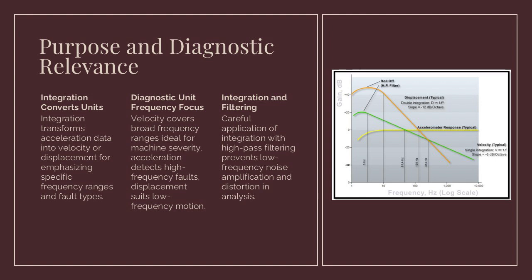Acceleration is ideal for detecting high-frequency faults such as early-stage bearing or gear defects, while displacement highlights low-frequency motion, making it suitable for slow-speed machines and journal bearings. By integrating data, analysts can tailor their analysis to the specific fault conditions they are investigating.